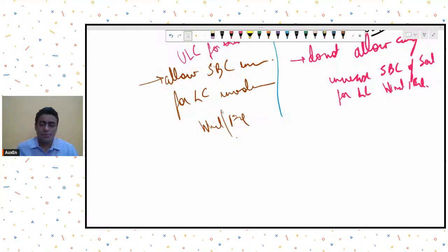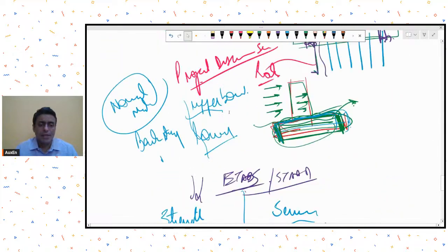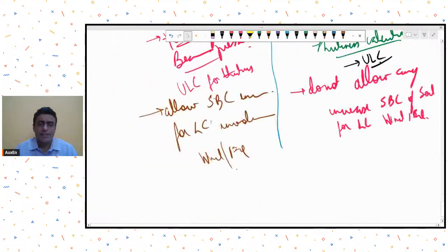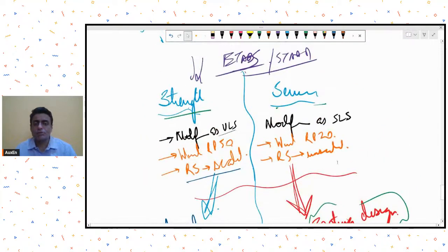Now, his main question was that in such cases, how do we maintain these two models? For example, if you were going to take the service model for footing design, and due to beam reinforcement requirement or column reinforcement requirement, you changed a few sizes in your strength model, then your service model will have some different sizes and the strength model will have some different sizes.